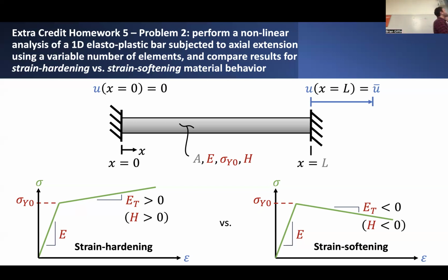And then for strain softening behavior, do you think I would get a different answer depending on how many elements I use in this problem? I see one head shaking yes. So intuitively, that's true. You'll get different answers if you're using strain softening and you're using a different number of